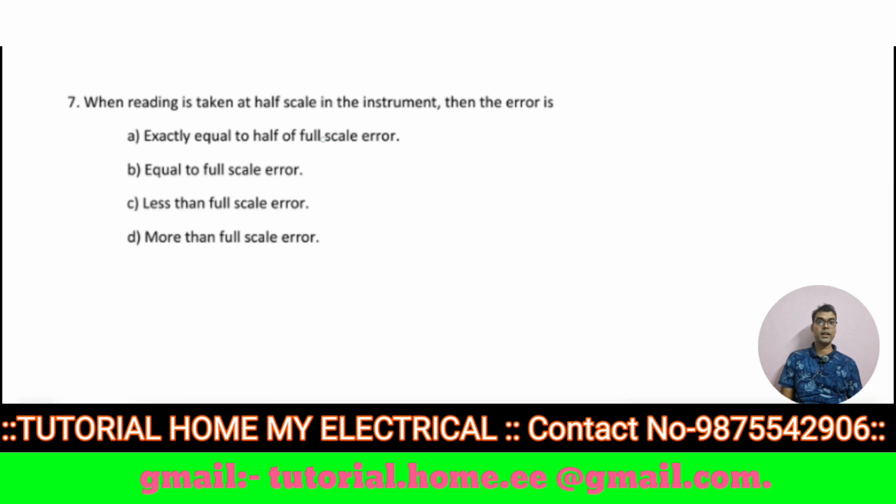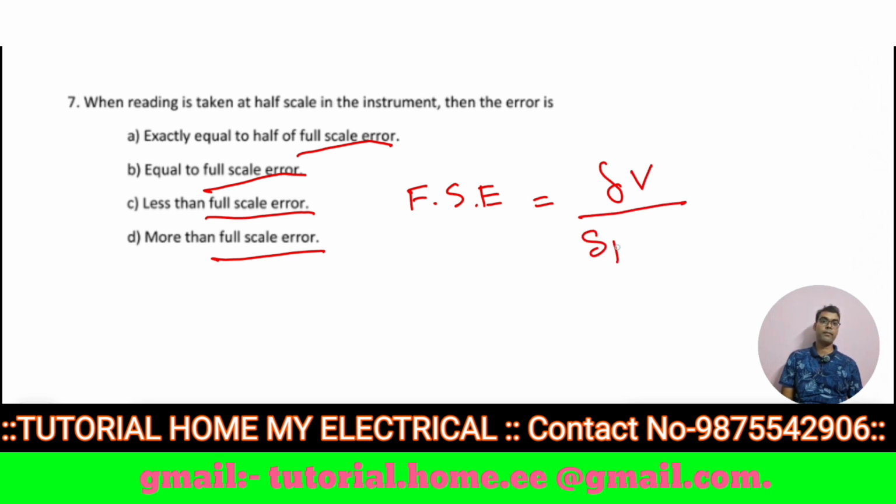What is full scale error? We denote the full scale error FSE as equal to absolute error by span into 100%.